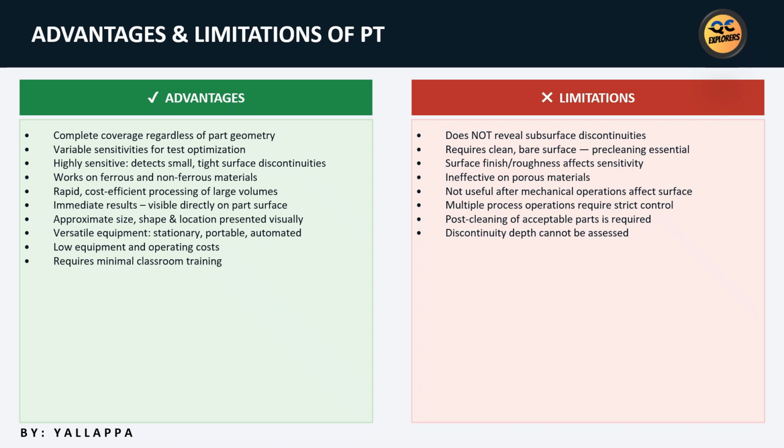And finally, PT cannot determine discontinuity depth. It only tells us that the defect is open to the surface. It does not tell us how deep the crack extends internally.